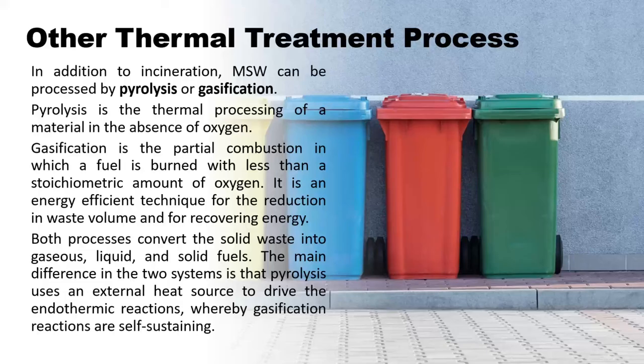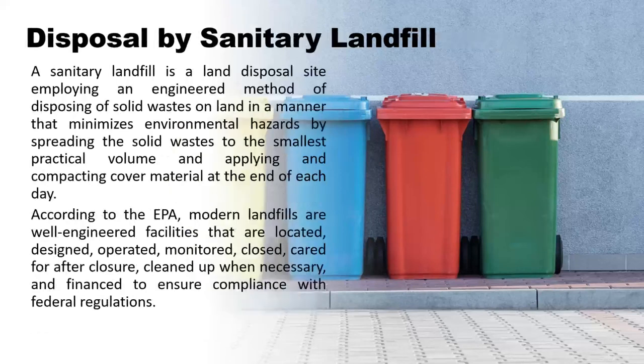It is an energy-efficient technique for the reduction in waste volume and for recovering energy. Both processes convert the solid waste into gaseous, liquid, and solid fuels. The main difference in the two systems is that pyrolysis uses an external heat source to drive the endothermic reactions, whereas gasification reactions are self-sustaining.